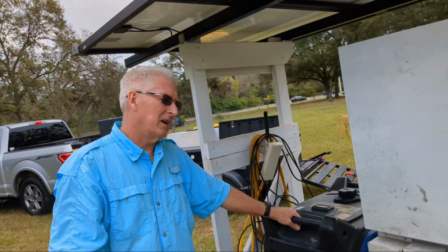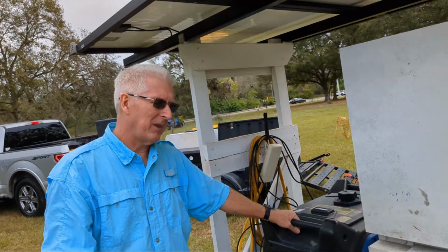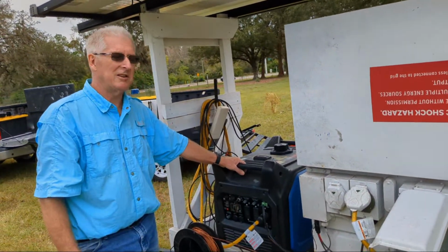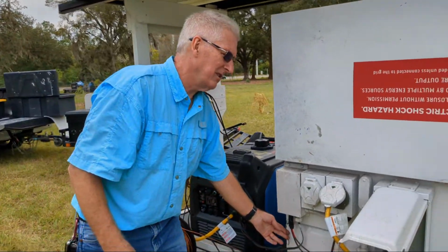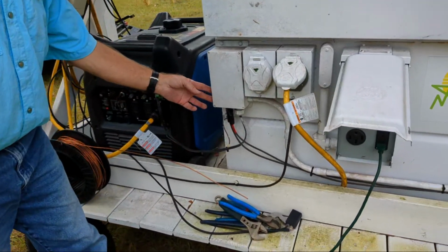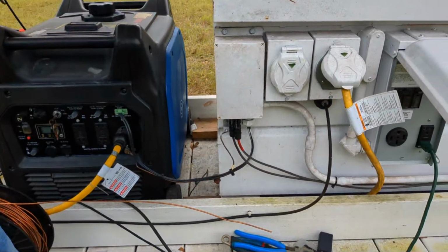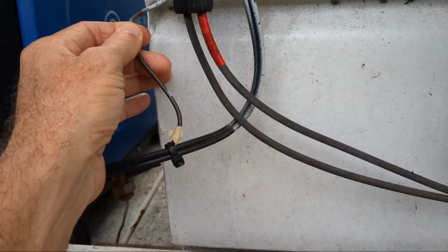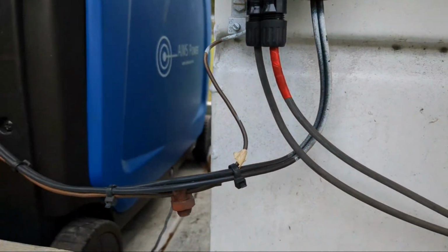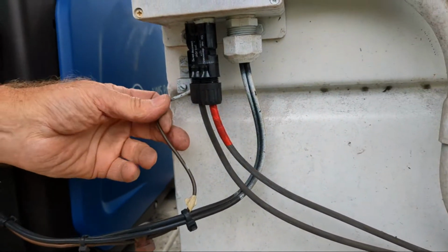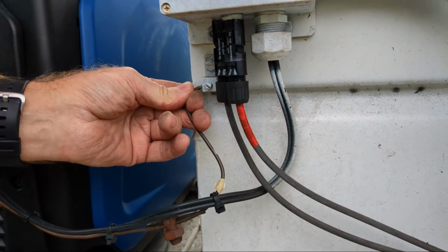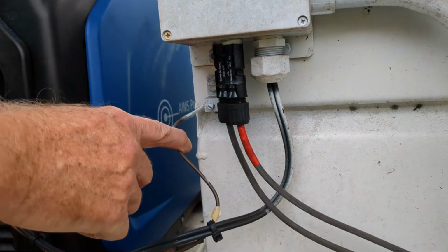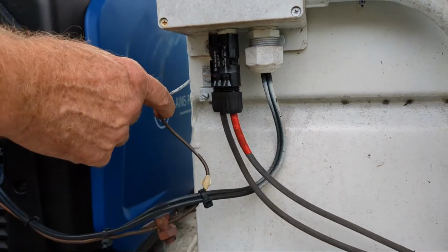In this power system, there is no polarity to the ground. It's just the ground. And we're using it to bond all the metal parts of the power station with all the metal parts of the generator. That's a huge problem, and that's probably why we're missing our wire, because they probably both came into here. And this needs to be tightened. So we're going to make one in here now. I didn't loosen that, by the way, but I would have in a moment.